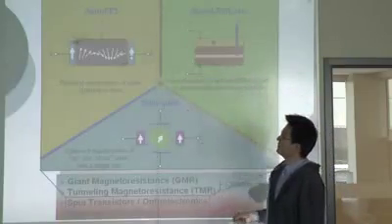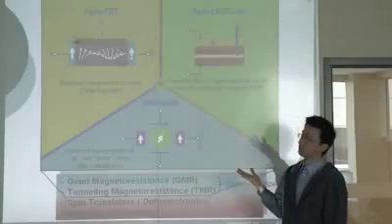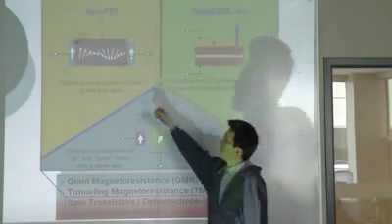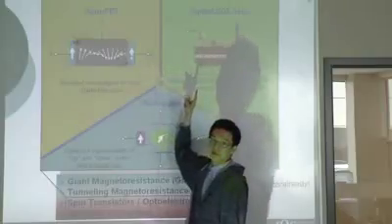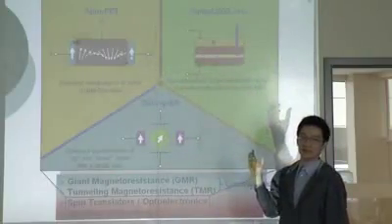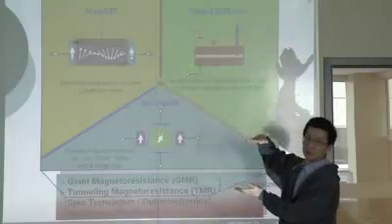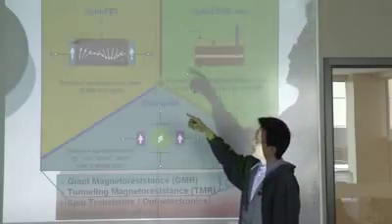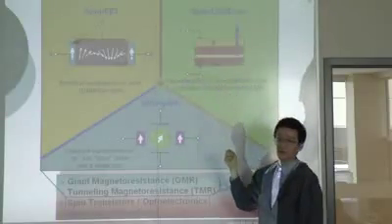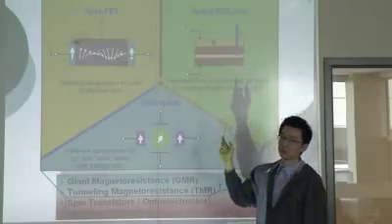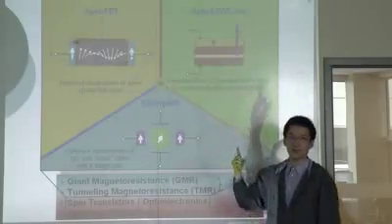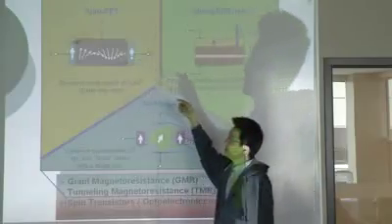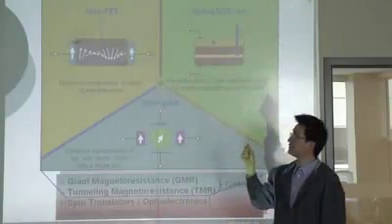A transistor. A spin-based transistor takes advantage of the field effect. What is really behind it is the special relativity. Now you can imagine if we have an electron flying through this channel, the electron has a finite velocity, and we can apply an electric field, we call it a gate voltage, to modulate the electron spin orientation. What happens is, if you look at in the rest frame of this electron, the electric field will actually transform into a magnetic field. Then the electron will start precessing around this magnetic field.